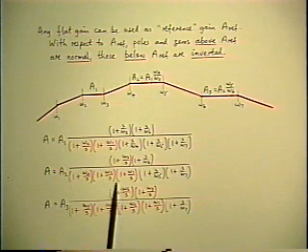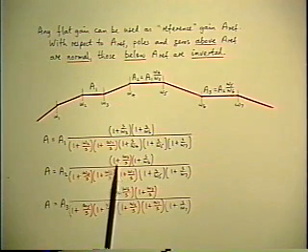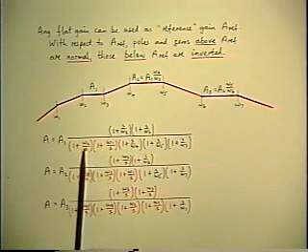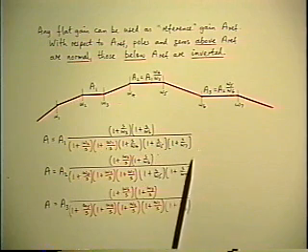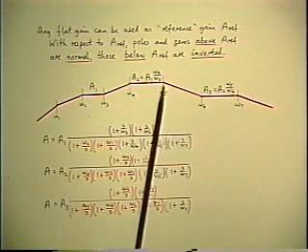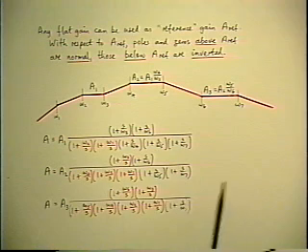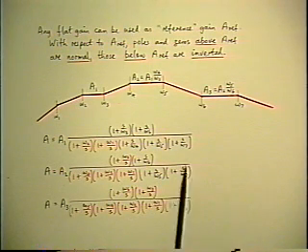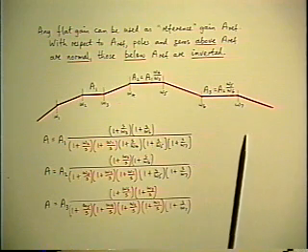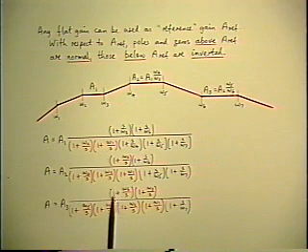And I chose red also just to illustrate more clearly the difference between whether the corner frequencies are inverted or normal. So you see those below the chosen reference gain are inverted, those above it are normal. So now you have the full symmetry of the two directions of frequency, and it's useful to get equally adept in writing the result in any form or any combination in order to expose the most useful things.